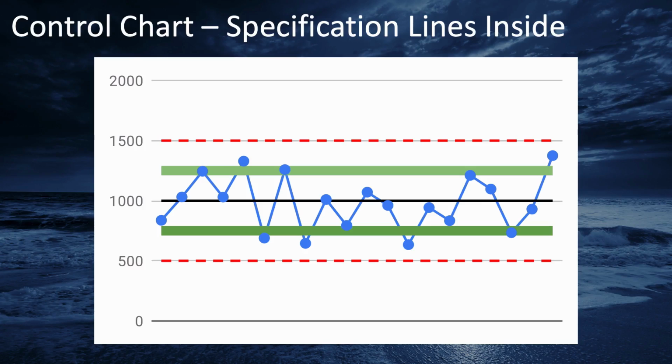On the other hand, you could have specification limits that are within or more restrictive than your control limits. We saw this with the truncated histogram, showing that some of the outputs of certain processes are unacceptable and need to be reworked or discarded. Your options are to improve your process to tighten up the control limits, or renegotiate the specifications, or live with having to rework or discard some of your outputs.